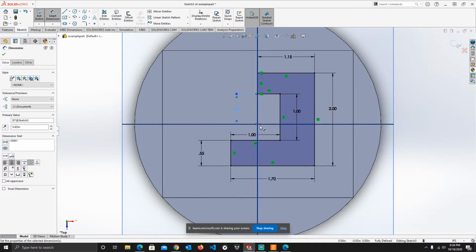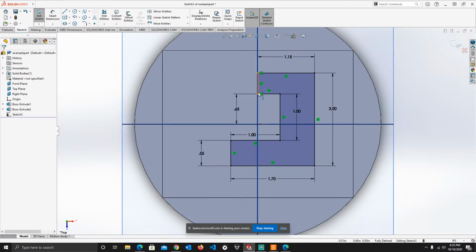You might be thinking, but okay, so you gave it a dimension on the vertical, but you didn't give it a dimension on the horizontal. Well, that's the reason why our lines here that were coincidental with our vertical come to work. Because we're basically set in our logic here when we made this figure is that this object is coincidental to this vertical line.